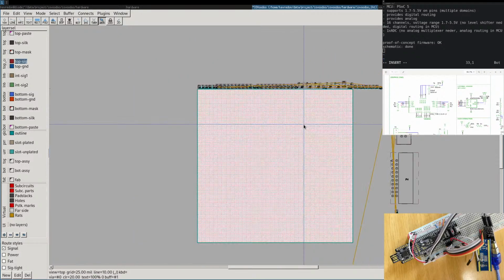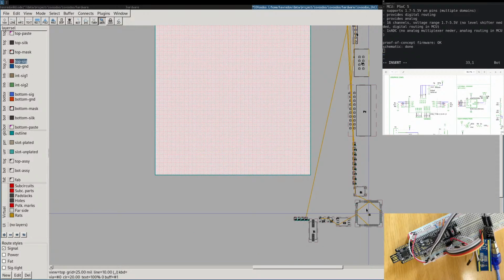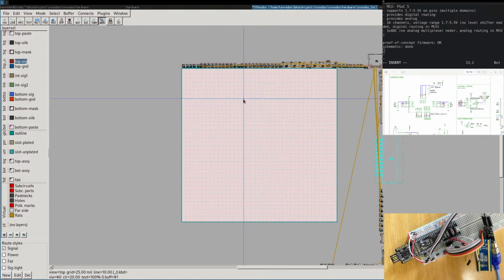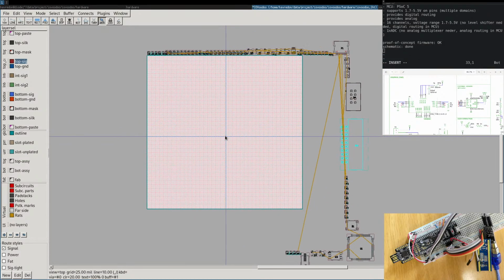What we also need to do, so this is the maximum board size, and it's plenty enough. You see, we have only one microcontroller. It is large, but the largest component is the connector, the 20-pin IDC connector, right angle, so we can connect here. Although I thought my board would be a bit smaller, but with all the components, it could take 5 by 10. We'll see how compact. We don't want to make both sides, double loaded. We could, because it's done by hand. So double loaded means that on a PCB, like something like, okay, the camera doesn't work anymore.